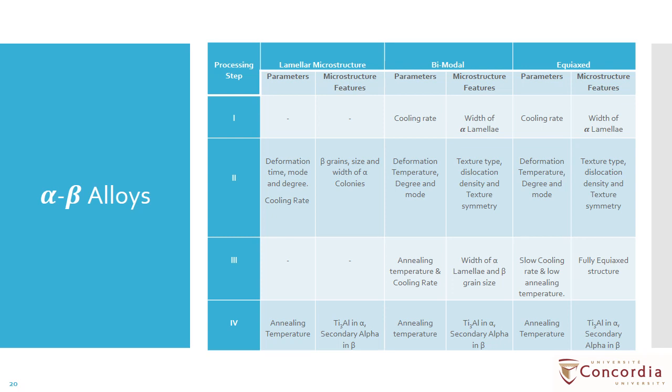Processing titanium at high temperatures can result in various types of alpha and beta matrices, leading to fully lamellar, fully equiaxed, or bimodal microstructures. Remarkably, the bimodal microstructure demonstrates exceptional strength when grain size is refined to the nanoscale, creating numerous boundary layers that hinder the dislocation movement. In specific applications, different elements are introduced to stabilize titanium or enhance specific properties.